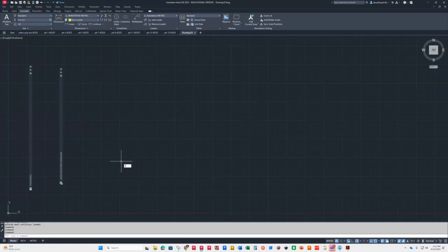All right, so first thing we're going to do, limits. 0,0 is the bottom corner, then the upper corner. What are we going to do? It's 450 by 250 by 225. That's pretty big. So let's see, that's going to be close to 700. So you know what? Let's just go all out. Let's make it 1,000 square. 1, 2, 3, 1,000, comma, 1,000.